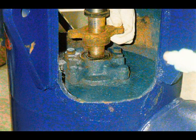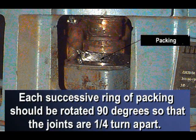Install one ring at a time. Make sure that the ring is clean and has not picked up any dirt. Lubricate the ring with Teflon grease or another appropriate lubricant. Successive rings of packing should be rotated 90 degrees so that the joints are a quarter turn apart. Each ring should be seated with a wooden block or split sleeve.